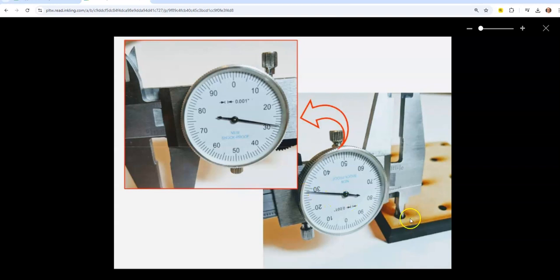that specific hole. And in this case, the measurement here would be 0.229. Notice how it still has a zero here. We're at 0.2 of an inch. So we'd say 0.2, and then after that, about 0.29, maybe right a little bit between 0.28 and 0.29. That's what the size of that hole would be.